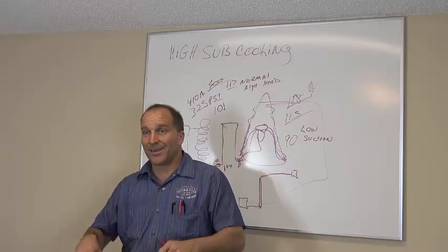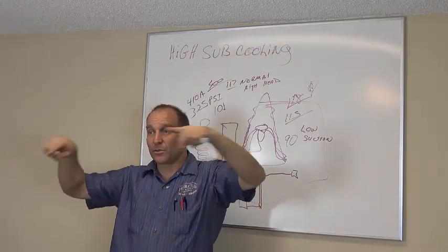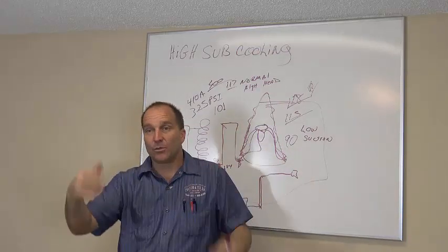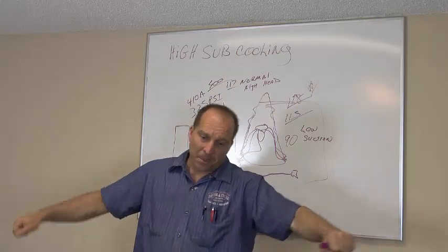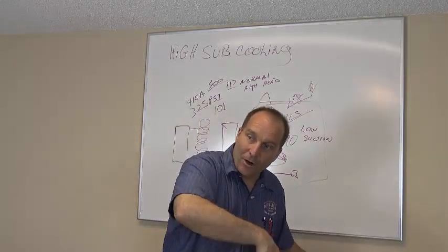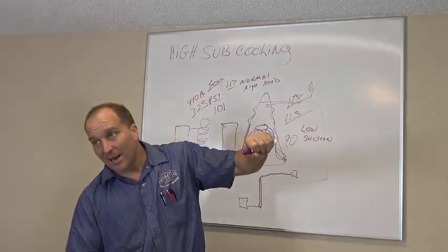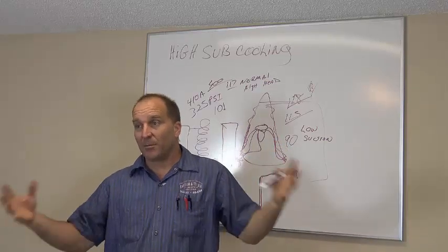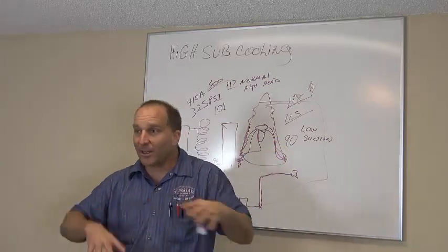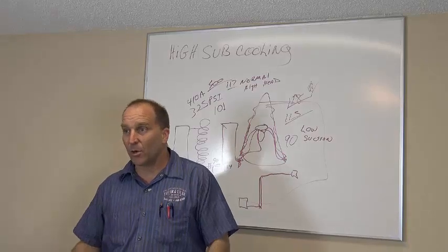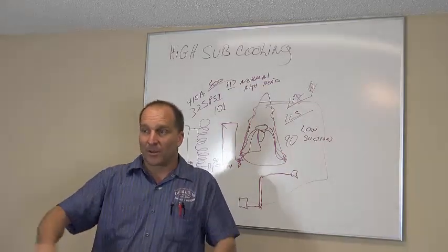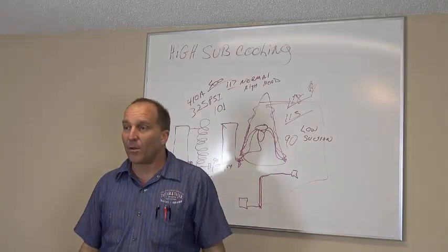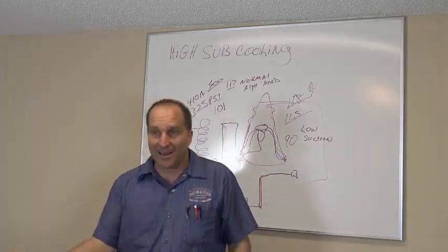Okay? You got to take the top off of it, which is 15 screws all the way around it. You got to take the 2 sides off of it. You got to kind of bend the other 2 sides out. You got to hose down the big dirt on it. Then you got to shoot from the inside out, just with the hose, just to get the big stuff off of it. So you're cleaning it once like that. Then you're going to spray it down with the chemical and bubble everything out of it, foam all the dirt out of it. Then you got to hit it down again.